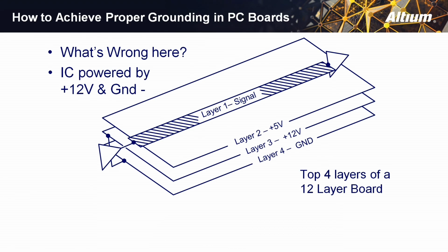So then I asked the question, why is that a 5-volt plane? This guy got really mad. And he said, that's a really good question. This was a ground plane originally. He called someone up and found out eventually that when they added some 5-volt buffers in the back corner of the board to bolster the signals at an I/O driver, the guy doing the layout asked, where can I find a plane to put 5 volts in the board? And one of the engineers told him, oh, just change one of the ground planes in the board to 5 volts. So he happened to change this particular ground plane to a 5-volt plane. They changed this back to a ground plane and the problem went away.